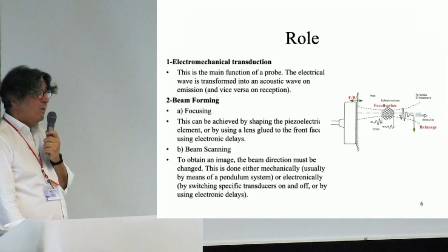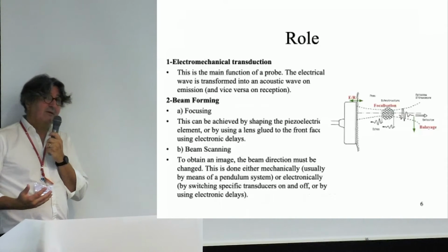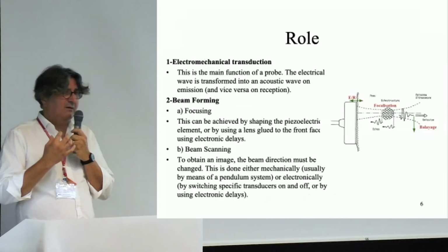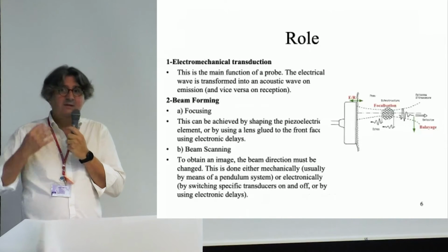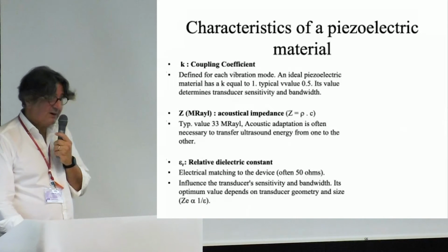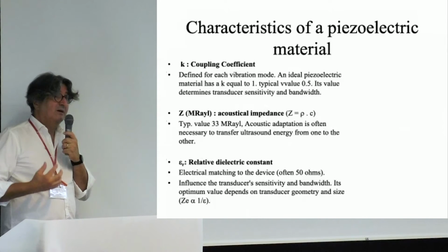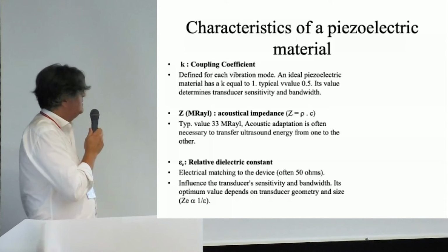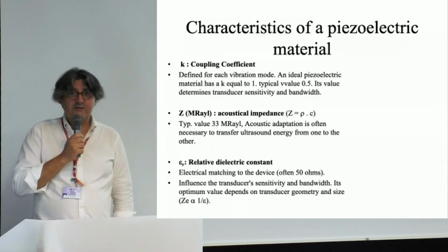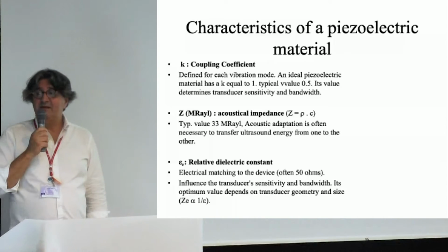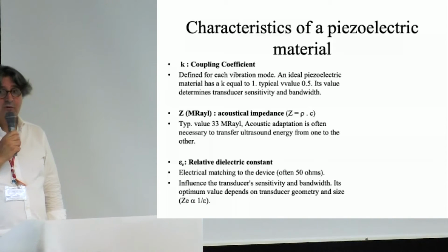Now, as I've already talked about, the heart of the transducer is the piezoelectric material. So what are the characteristics that are very important for analyzing the transduction phenomenon? First, this is the coupling coefficient. And as I said, it is defined for each vibration mode.